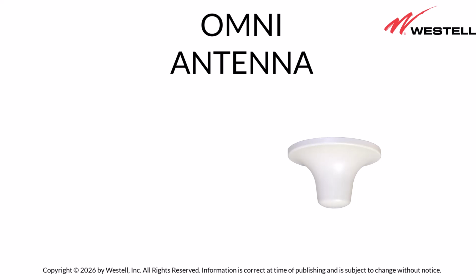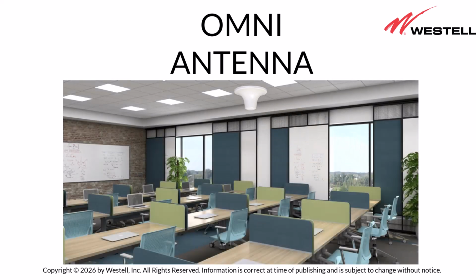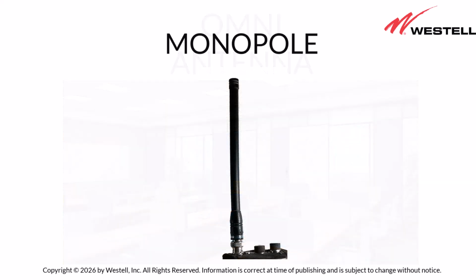It is important that these antennas are mounted on the ceiling so they radiate throughout the area. If mounted sideways on a wall, they would cover only the ceiling and floor. Not exactly what is intended. The antennas on portables are monopole antennas. Monopole antennas are ideal for this application because they require half the length of a dipole.